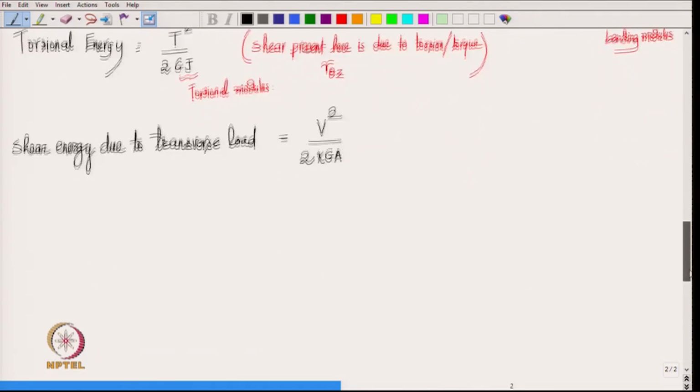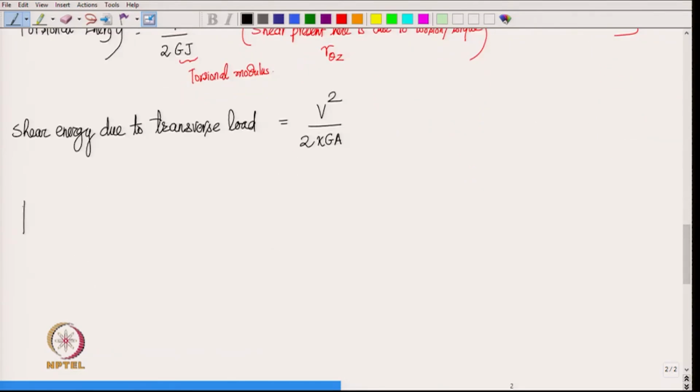So, basically when we have a beam, suppose it is clamped at one end, then we will have some force in the cross section, which is the vector V, and some moment also in the cross section, vector m, and the shear force V you can then decompose into 3 components. One along the axis, V x, we will call it P, the axial force, and then in the cross section V y and V z.